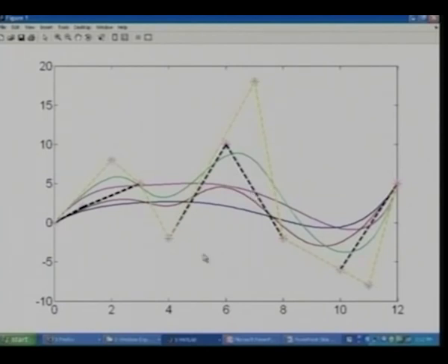Look at how closely the B-spline curves follow the undulations reflected by the control points, or the control polyline for that matter. Why do you think this is possible? It is because of the strong convex hull property, or the strong local barycentricity that the B-spline basis functions have to offer.